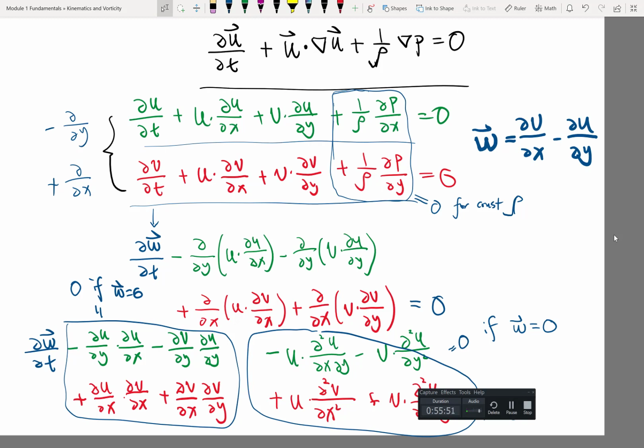And actually, if you can start to infer the pressure, you can start to see the high pressure region and low pressure region is going to exert a pressure gradient force to the flow field. And if the pressure gradient force lies orthogonal to the streamlines, it'll turn the streamlines, right? If the pressure gradient aligns with the streamline, it'll accelerate or decelerate the streamline. So basically, you can start to really use these principles to infer a lot of information from a flow field that you wouldn't just directly be able to see.